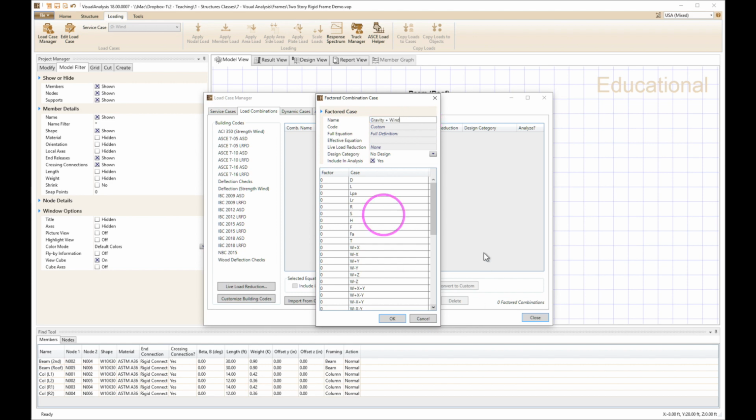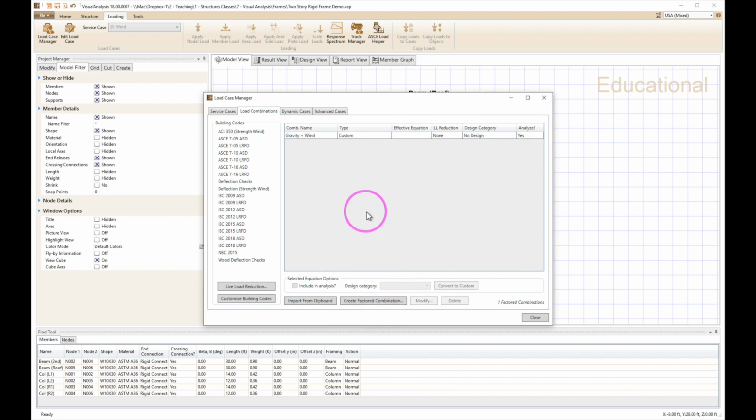And down at the bottom you'll find the gravity and wind loads. We're going to put a factor of 1 on these, so it's 100% of gravity and 100% of wind. All of these different specifications have many different combinations with different factors, less than 100% or even more than 100%, to cover the greatest probable likelihood of any of these happening at the same time.